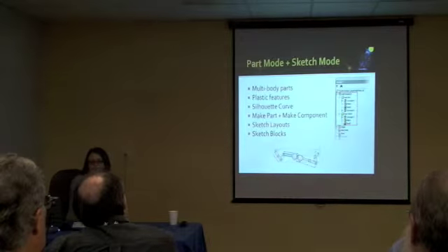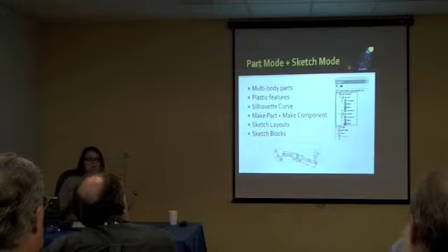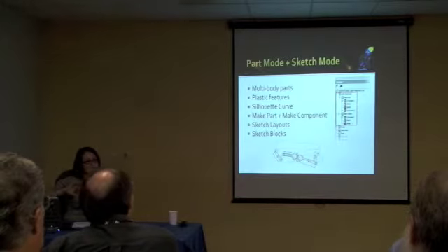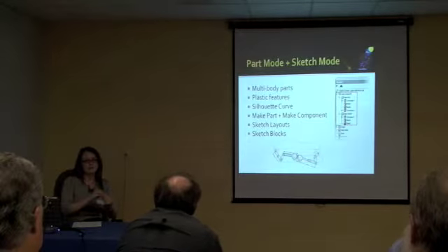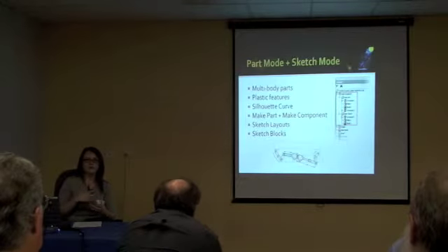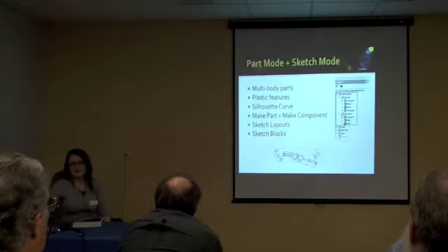And there are these new things called sketch layouts and sketch blocks. This sketch block concept's interesting to me. What you can do is save a sketch, store it in your template, and just insert it whenever you want it. Sketch blocks, I believe, come from AutoCAD terminology. You get a configuration of a sketch, you dimension it, you constrain it however you need, and you can save that configuration of lines, constraints, and dimensions to a block, which enables you to insert it at any point in time. So if you've got common things that you're sketching all the time, it might be worth creating some sketch blocks. I'll display them in a moment too.